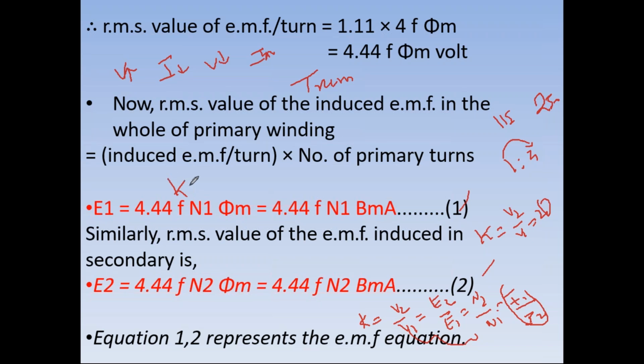So we represent the power of a transformer in terms of kVA rating, but in the case of a generator and motor we represent it in kilowatts. Only the transformer's power is represented in terms of volt-ampere. The reason is that we have two losses in the transformer.